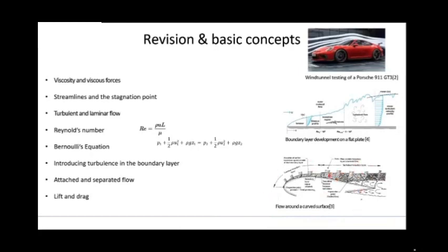If our boundary layer is still connected to our object, then if we see any reduction in pressure on the top of the object because of Bernoulli's equation, obviously that would try and lift our object. So the definition of lift: we're trying to lift our object because we're seeing a reduction in pressure on top of the object.